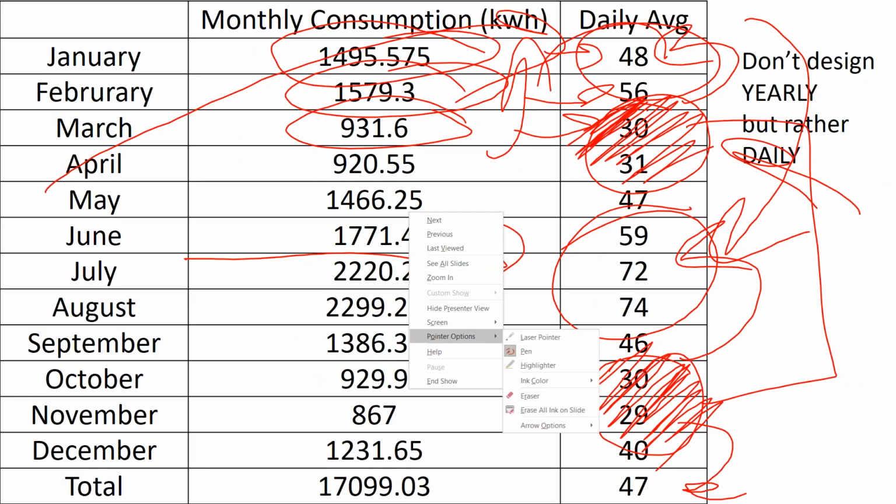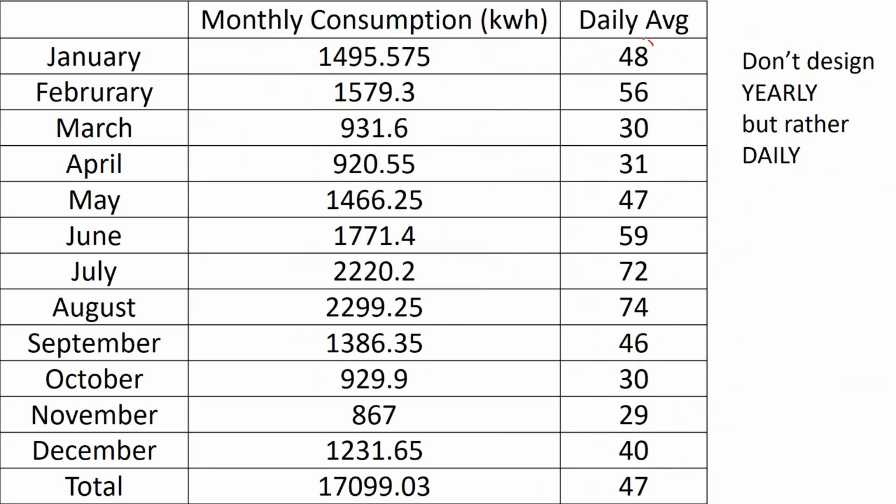We can take how much energy we're drawing out of the battery on a daily basis, and then graph it with PV Watts to determine how much energy we're putting back in on a given day. And the net difference, you can do that calculation for every hour of the day, every day of the year, and track how much energy is going into the battery and how much energy is coming out of the battery. And you can look at how deep you can discharge your battery technology, whether it be 35%, 65%, or 100%, and size your battery bank such that you don't run out of electricity.